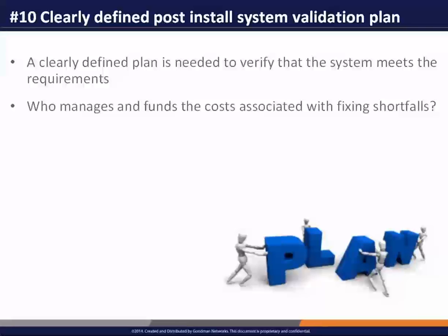And then finally, you've got your DAS built, and it's a terrific thing to be able to get that accomplished. But in the end, you need to have a defined means of validating. Did this thing that you had built, is it really meeting the system requirements? So there needs to be a post-installation plan, a validation plan as to how to confirm that what was installed is actually being delivered. And that can be done via a post-installation benchmark study, again, using a mapping tool or software. The installation teams will frequently have that equipment.